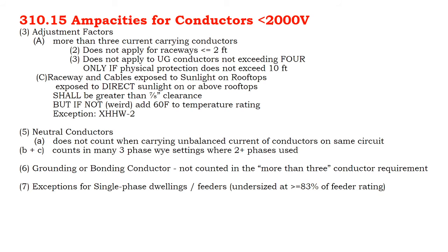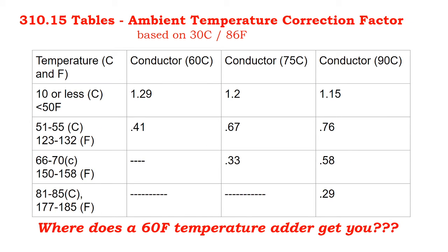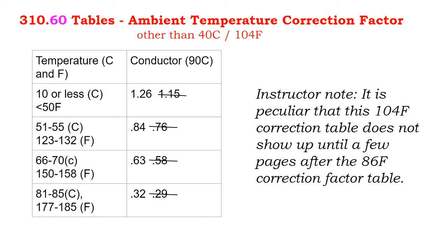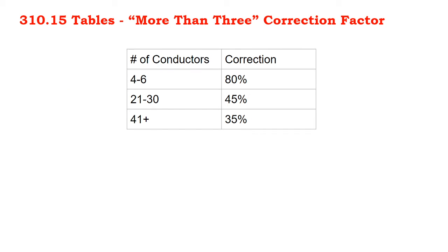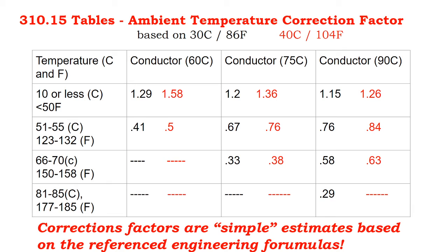Temperature becomes an issue as well up on a rooftop. So we talk about how conduits and conductors are adjusted for temperature and how to read the temperature adjustment tables. So we'll leave that for detailed discussion. We're just trying to get through the summary right now. There's ampacity adjustments for putting more than 3 cables into a conduit. The cables themselves heat up and require additional ampacity correction.